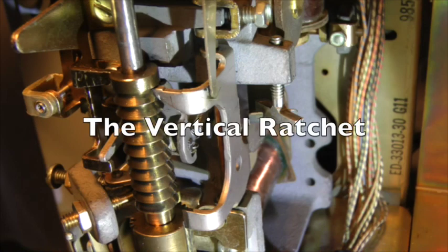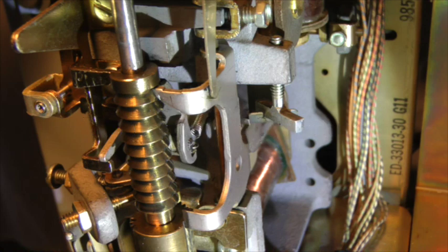Moving downward along the shaft, the next item of apparatus that is fixed to the shaft is the vertical ratchet. The vertical ratchet is one of several devices involved in stepping the shaft vertically upwards. The ratchet has 10 teeth. Each ratchet tooth is associated with a vertical step to a particular bank level. The top tooth is associated with level 1. The one below that is associated with level 2, and so on down to level 9 and finally level 0. Here's a slow motion clip of the ratchet being raised 10 vertical steps.